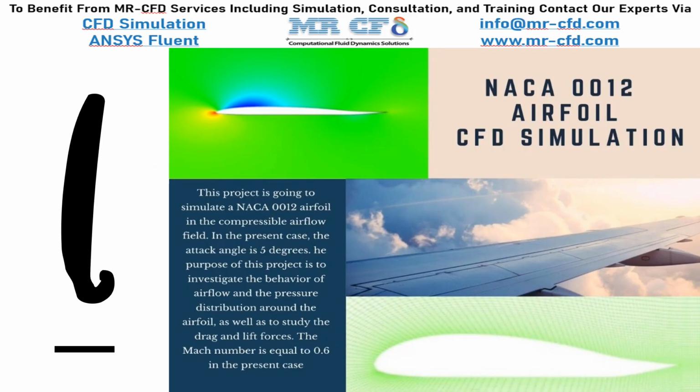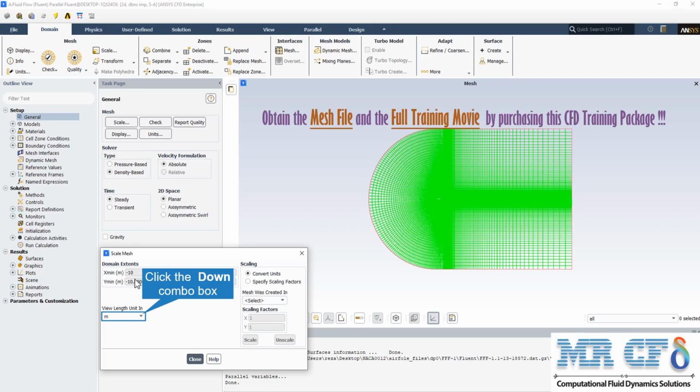In this project, we are going to simulate a NACA 0012 airfoil in the compressible airflow field. Domain extents displays the Cartesian coordinate extremes of the nodes in the mesh. We should note that these values are not editable, they are purely informational. Also, X, Y, Z minimum shows the minimum values of the Cartesian coordinates in the mesh, and X, Y, and Z maximum shows the maximum values of the coordinates in the mesh.